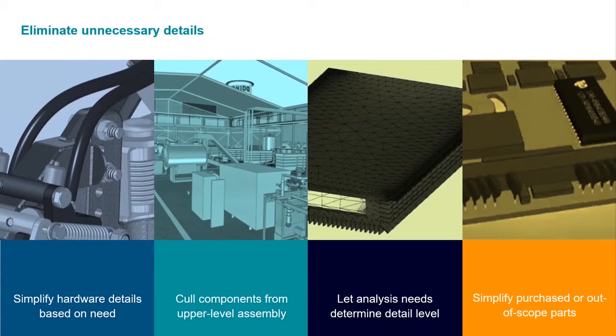One of the biggest impacts you can have on your assembly performance is to simplify your parts, especially if they're reused often. For example, if your model includes a lot of hardware, you likely don't need all the little details, things like helical threads, markings on the head of a bolt, or small fillets. We don't need those to show up in the bill of materials or the drawing necessarily. Now, if showing the head shape and the body of the screw extruded to the correct depths are sufficient, then simplifying your part accordingly will help out a lot.